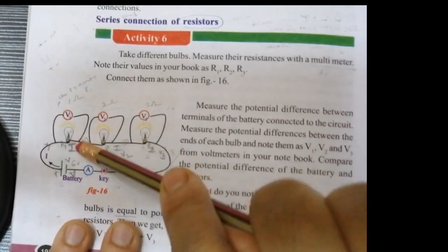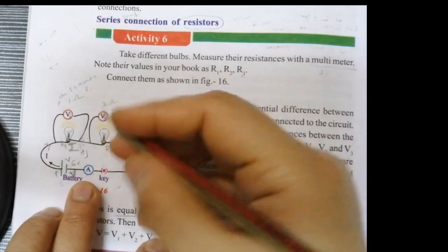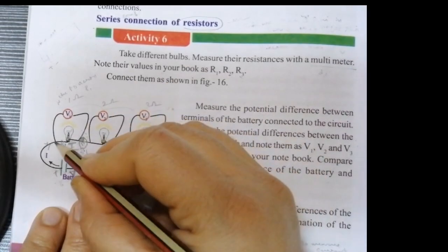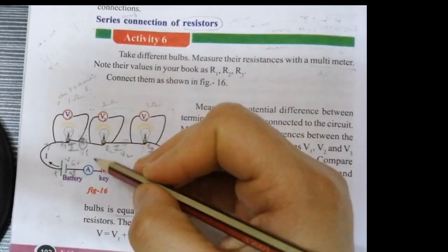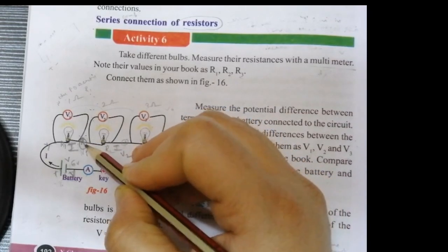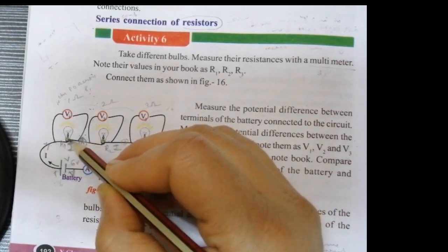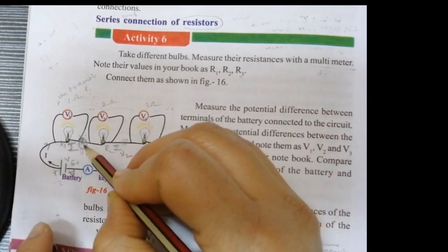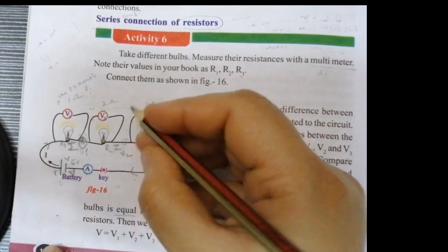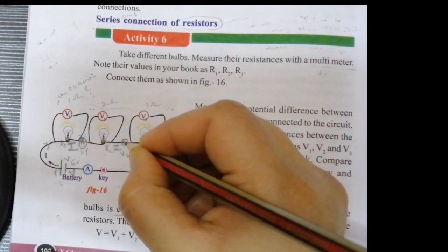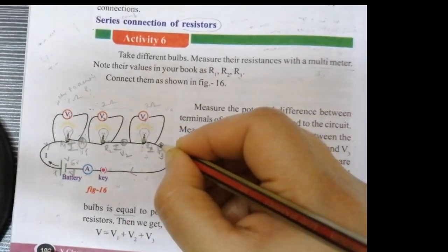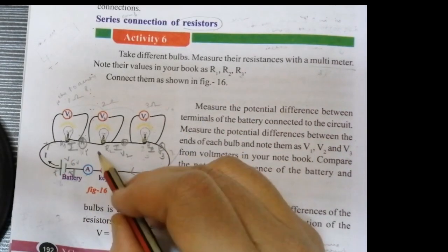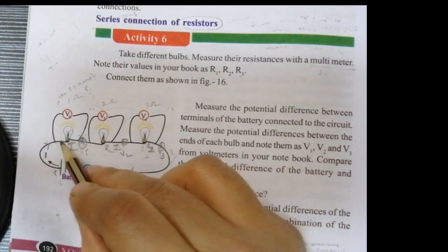Okay, suppose instead of placing the ammeter here, I'll place the ammeter in between these terminals. Then I'll come to know what's the current flowing. The ammeter gives the reading of the current flowing in this resistance, isn't it? The current flowing in this resistance will be given by the ammeter, and for the current flowing in this resistance, I'll arrange another ammeter here. Again I'll arrange one more ammeter here. By arranging this, it will be easy for us to know the current in each resistor.